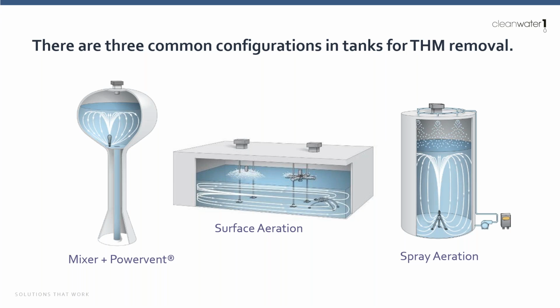So you can start to see here the common types of systems: mixer plus power vent. Again, simple as it gets. Mix the water, blow air through the headspace, volatilize off trihalomethanes. Ideal for tanks with significant storage time.